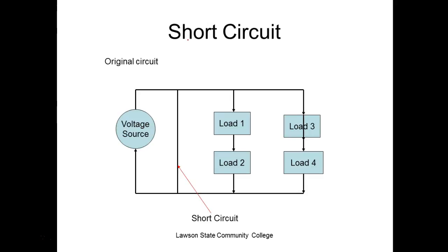So notice the difference. I could have put the bar here, I could have put the bar there. But what we do is, anything where we connect the two conductors that come from the voltage source, if we connect those two conductors together, this is a short circuit.